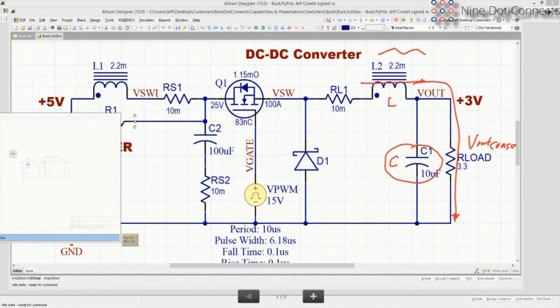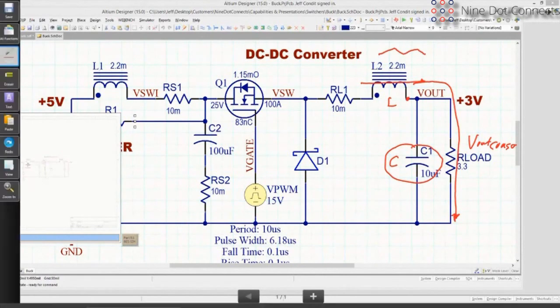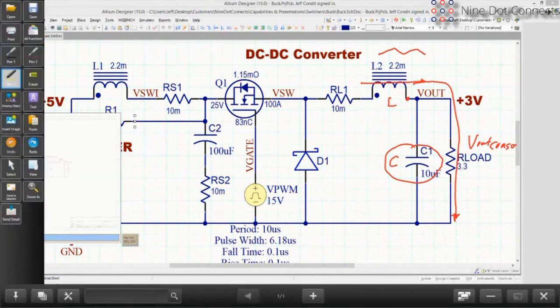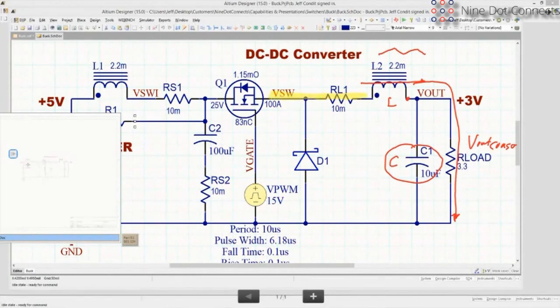If Vout is constant, then this end of the inductor is going to be fairly constant in voltage. And if it keeps a fairly constant current, the voltage at the switching node is going to be changing radically. Again, remember that the switching node is going to have a very large voltage change on it. So yes, we have back EMF. We have some AC form of back EMF from the inductance, but what that's doing is acting like an LC filter. If we didn't have that, then the switching voltage would be applied directly to the load, and the current would be going up and down with the voltage.